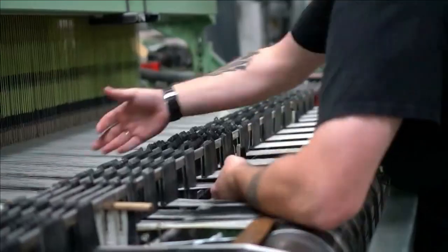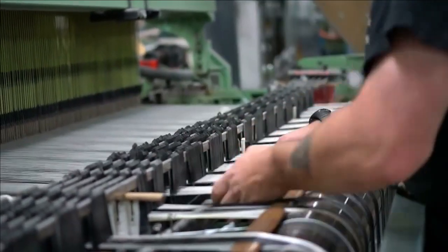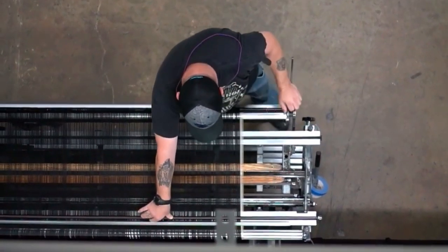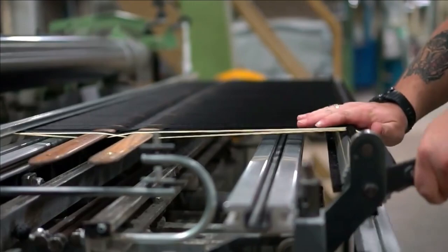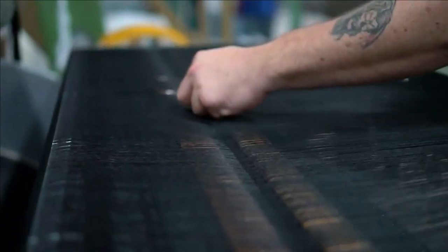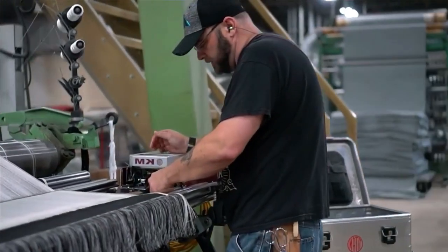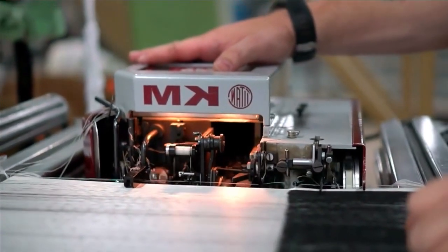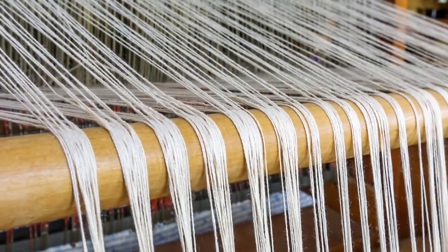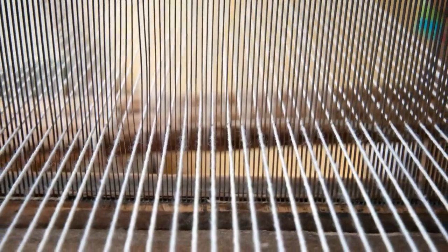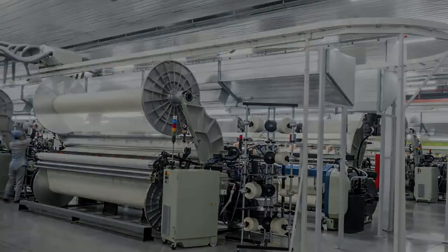Looming. At the start of the new warp, the tail end of the warp from the exhausted weaver beam is attached. It is called tying in. Therefore, the drawing mechanism may be excluded if each end of the new beam is attached to its consequent end on the old beam. All knots are pulled through the drop wires, heddles, and reeds after the tying in process. The loom is ready for use now.